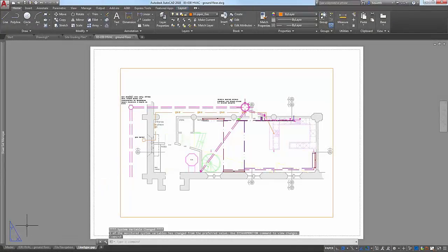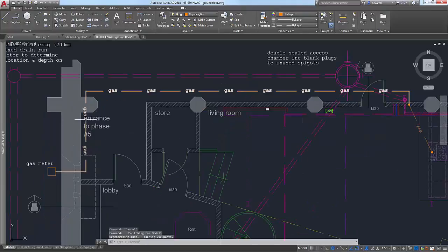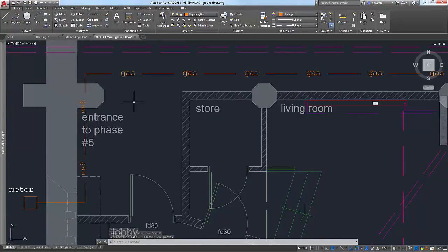Selection of line types is also improved in AutoCAD 2018. With line type gap selection enabled, you can now select and snap to complex and DGN line types, even on the gaps between the line segments. And you're not limited to simple geometry like lines and circles. It's supported by all objects, such as polylines that have a width and splines.